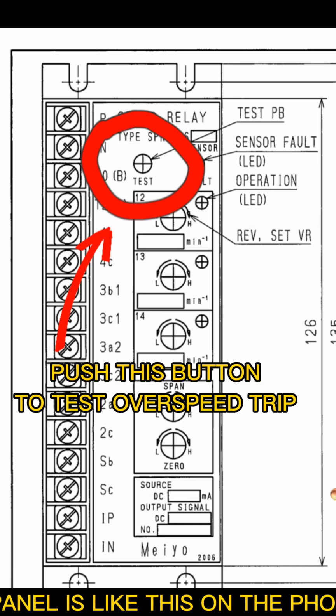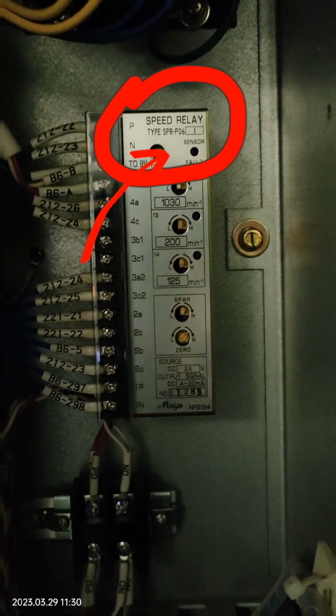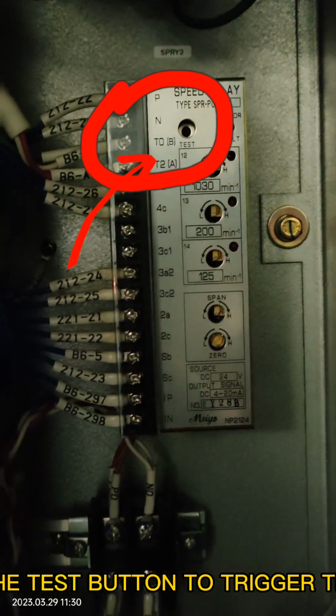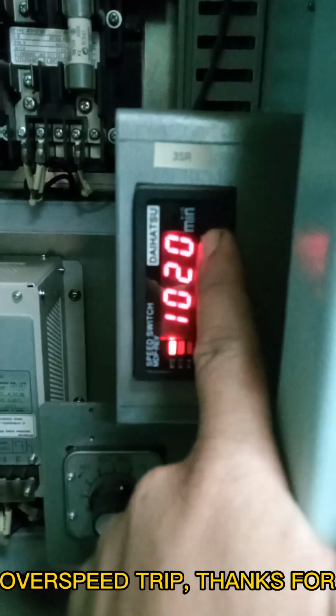Another speed switch relay attached on the auxiliary engine panel is like this in the photo. This speed relay is very easy for activating the overspeed trip. Just push the test button to trigger the alarm and trip. That's the testing of our auxiliary engine onboard for overspeed trip.